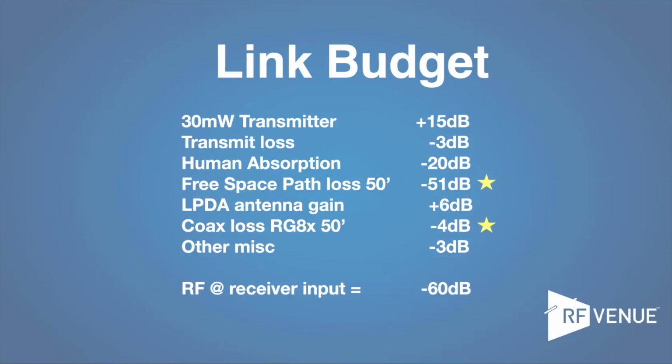Well, let's see. What we kind of skipped here was one thing that might happen because of that cable loss. If that was a really long cable and I didn't get a satisfactory number at the bottom, do I need to add a line amp in there? Right. So it depends. If it's a bad number, what we would prefer you to do is probably spend that money for better cable, better coax. But there's a place where that runs out, and you simply have to boost it to make up for the loss in the coax.